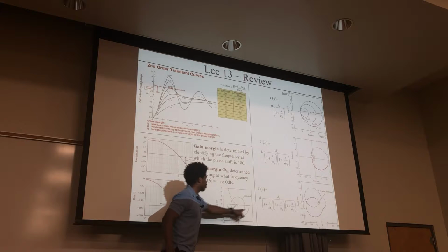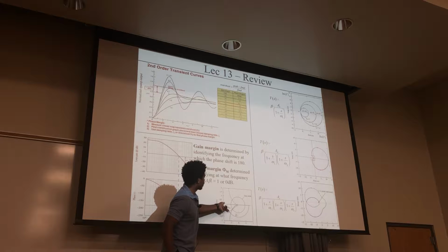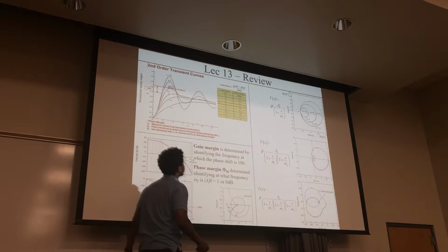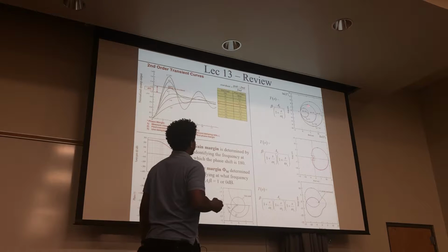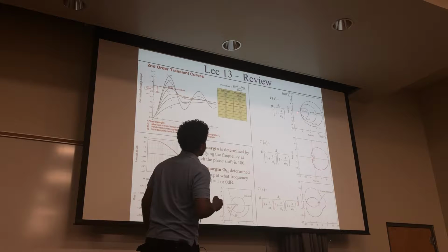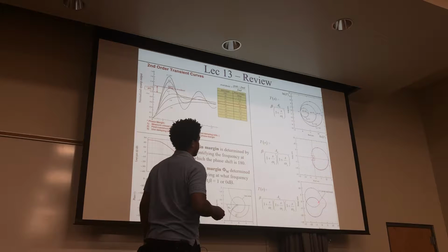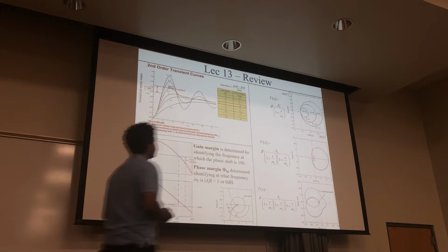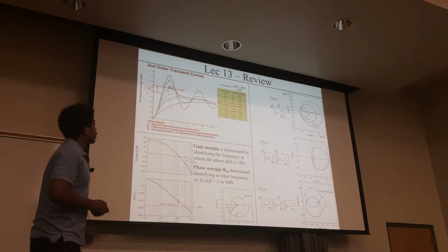What it looks like graphically in terms of the angle of the feedback gain right here, and also the phase margin right there, and what that looks like graphically in terms of this unit circle. And also for the first order, second order, and third order systems, looking at stability, where this is t equals -1 in all these cases. For the third order system, we see that this t equals -1 can overlap this lobe right here, and that's where you can get this instability. These two systems are stable, actually.